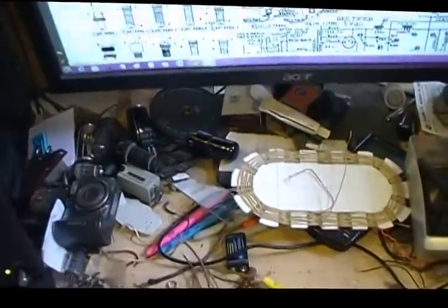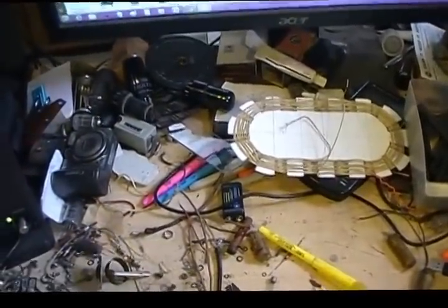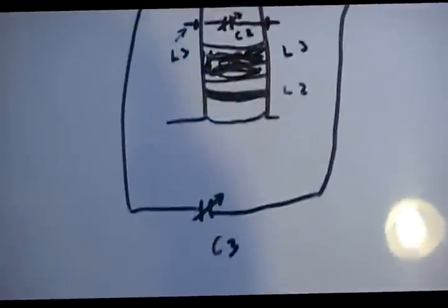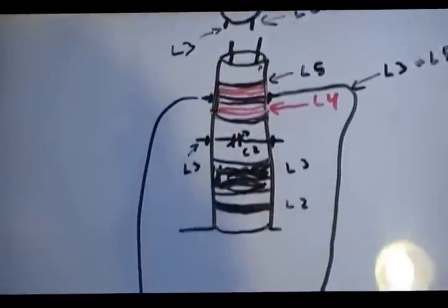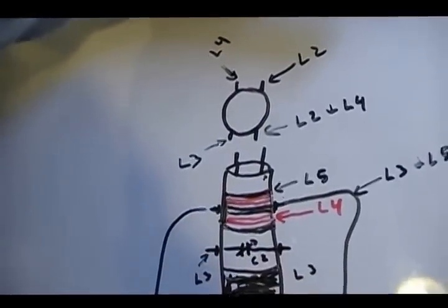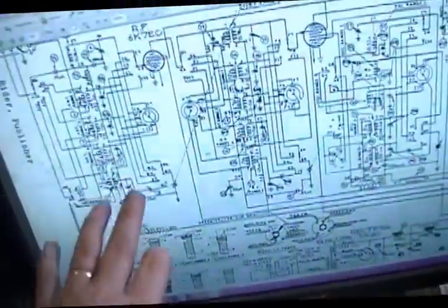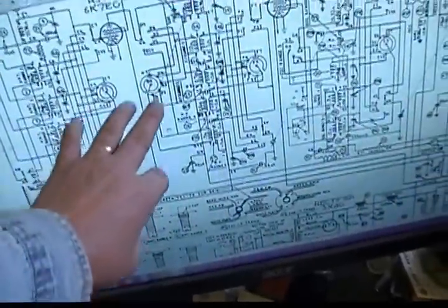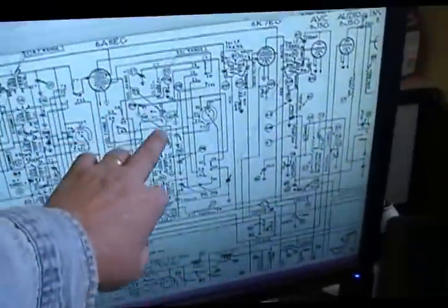But pictures, a lot of pictures, making your own drawing, mapping the coil out, which also helps you in establishing the coil's good. You know, you can measure it and check it and everything. Good, your own documentation, plus familiarity and the documentation of the schematic. You should know the schematic very well and know how to find everything that's on the schematic in the radio.